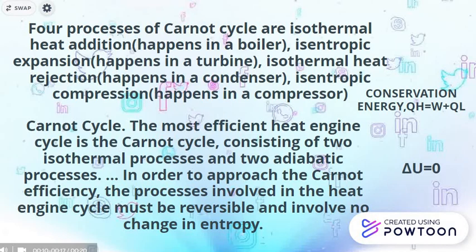We got that conservation of energy is QH equals W plus QL, where QH, W and QL are always positive. The change in internal energy of the system is delta U equals 0 because it returns to the starting state.